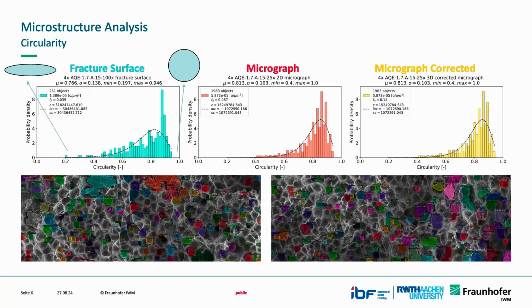If we analyze the fracture surfaces, we have the particles that are completely revealed because they take place in the fracture process itself. So if we have a weirdly shaped particle here, it's going to be completely observable in its entirety. Whereas if we just do a micrograph, it's very unlikely that we can actually cut this particle with this entire part.